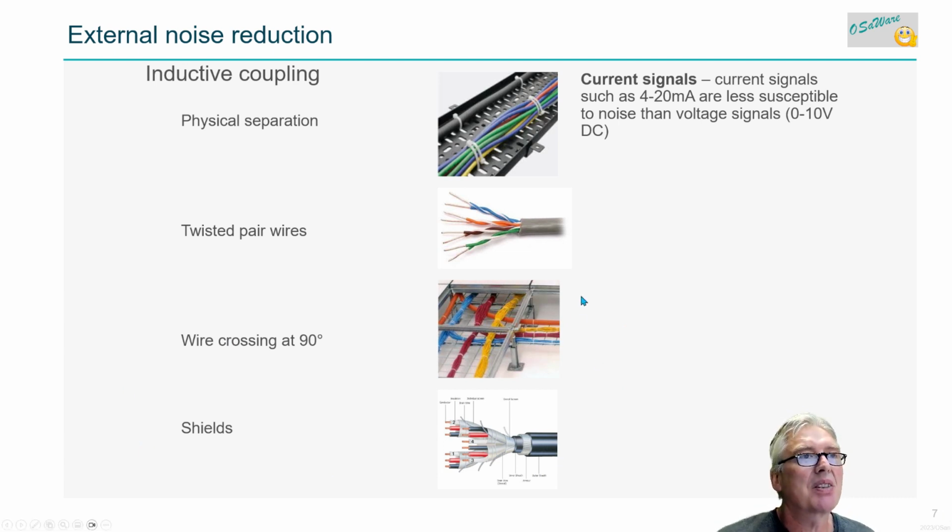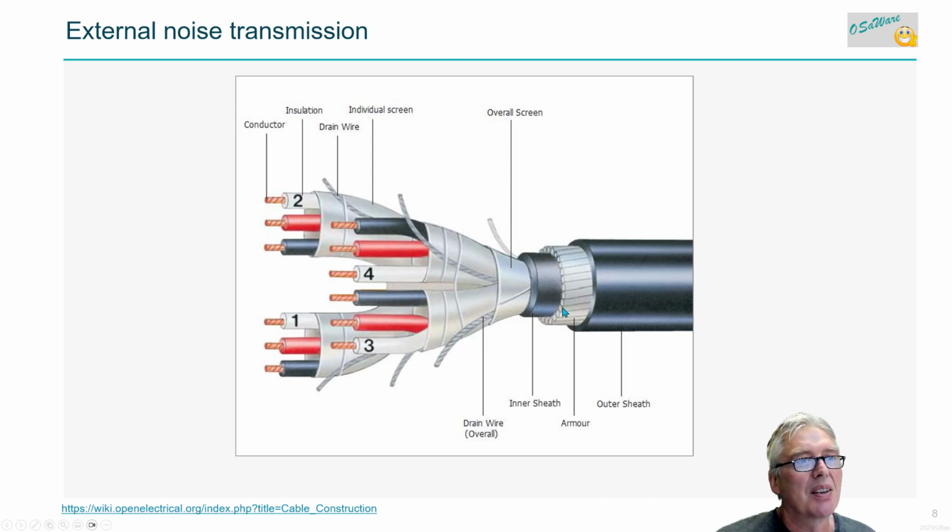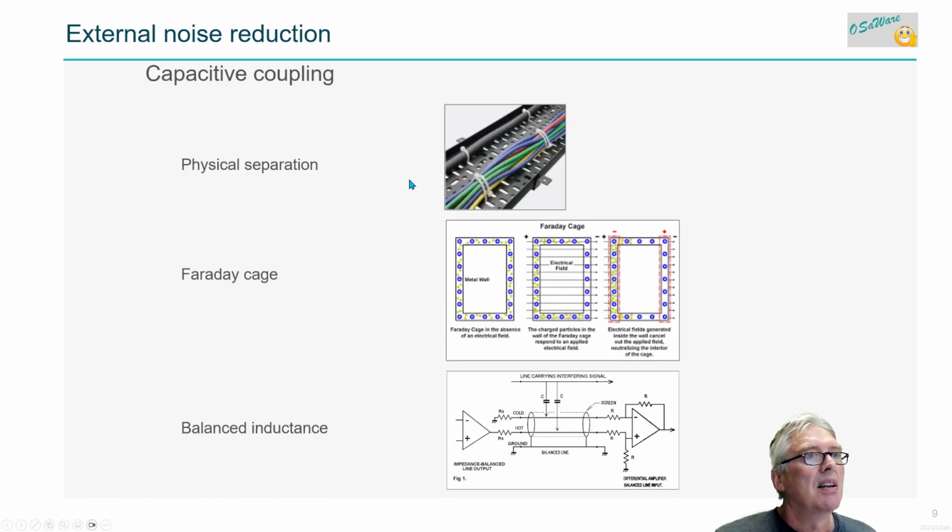And then we have shielding for electromagnetic fields. That's the principle of, let's say, the Faraday cage. No matter what kind of electric field you have on the outside, you don't get anything on the inside. So here is some cable. I think this is from, you might not find this figure anymore. But here we have maybe twisted pairs, and we have individual shields. We have drain wires, which drain whatever electrons are in, we drain them down to ground somewhere. And this plastic armor is just for the strength, and so on.